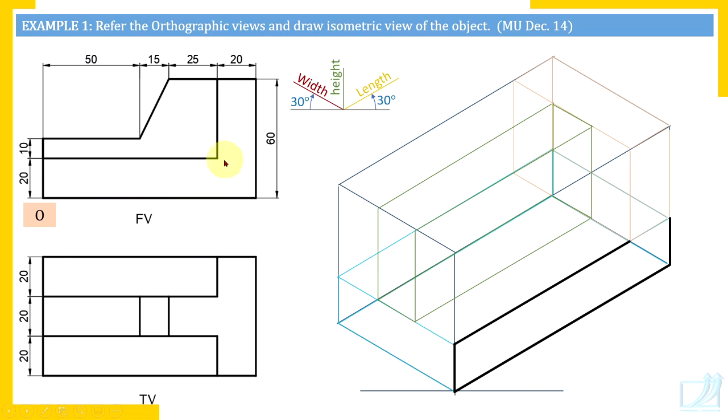In fact, other way around, there is no edge here that suggests you that vertical surface and the horizontal surface of the base plate, they are in one plane. And therefore, I have not drawn this edge. So front surface. Now our focus is on the base plate. Now left side surface edges. Why I have not made this line dark? So reason is, check here.